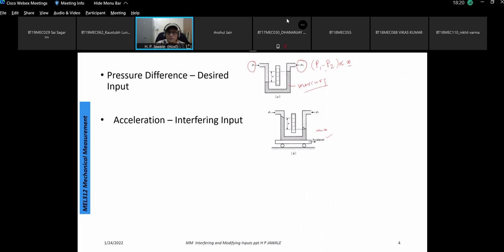Say for example, it will have the graduation here. Now you can see that this graduation has given rise to some unwanted effect here, and instead of this del x, it will show something else than what is the true input. So in this condition, we can assume that acceleration is going to act as an interfering unit. Why is it interfering? Because it has altered the input signal.